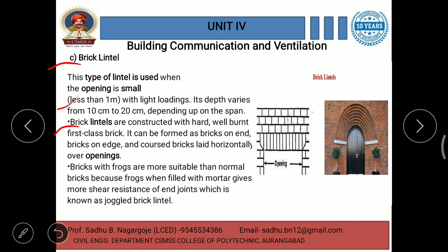Okay. Brick lintels are constructed with hard, well burnt, first class brick. It can be formed as bricks on end, bricks on edge, and courses of bricks laid horizontally over openings. So, this is about its construction. Bricks with frogs are more suitable than normal bricks because frogs, when filled with mortar, give more shear resistance of end joints, which is known as joggled lintel.